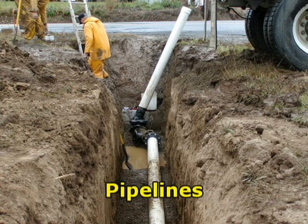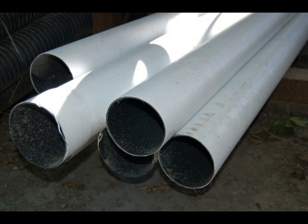Pipelines. Irrigation pipelines can be used for the same purposes as open channels or in place of open channels. Because the pipelines almost eliminate losses from evaporation and seepage, water distribution efficiency is high. They are particularly adapted to areas where seepage losses from ditches are high.